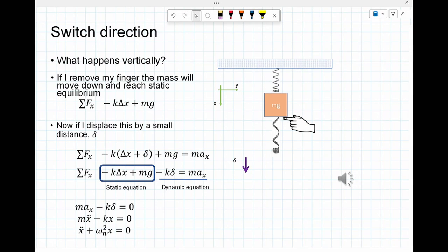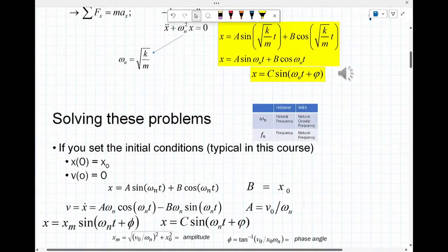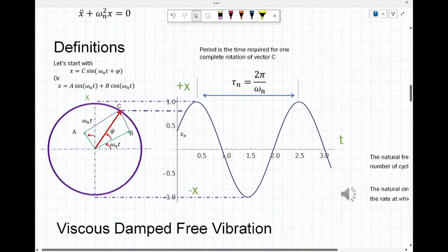But what we end up with, whatever this term is, is your natural circular frequency, which I should look at. Natural frequency, excuse me. I did this curve a while ago. Same thing. It's just showing you the parallels between the two cases, or the two solution formats that you saw: the natural period, tau n, is 2 pi over omega n, just like tau d is 2 pi over omega d.